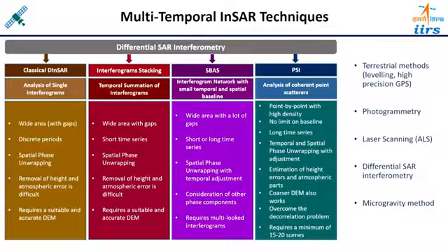But in PSI we are considering the persistent scatterer point itself. It means the phase and the coherence are very strong over those PS points, and whatever outputs come are highly accurate. But in classical InSAR only two images are combined, and if you are interested in time series analysis, such processing has to be repeated again and again.